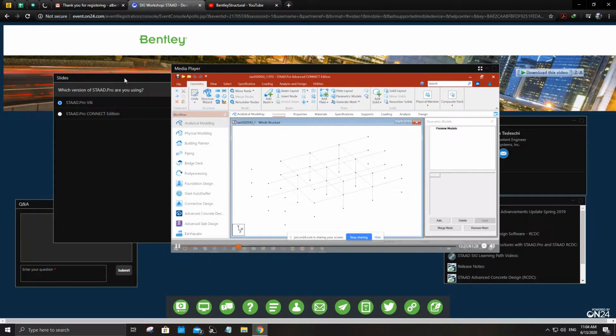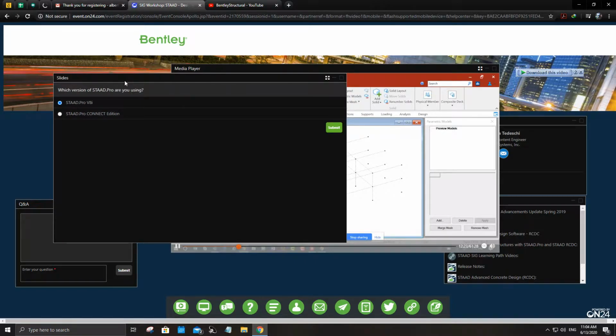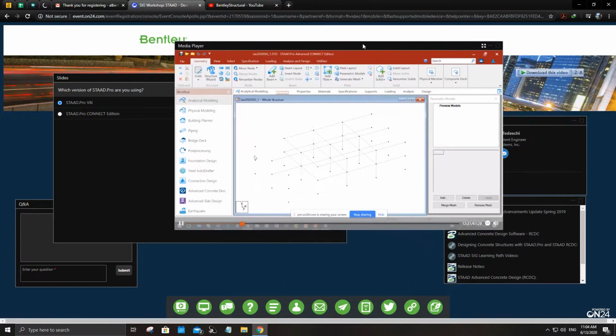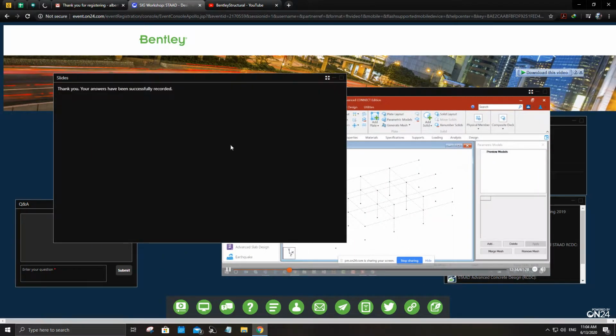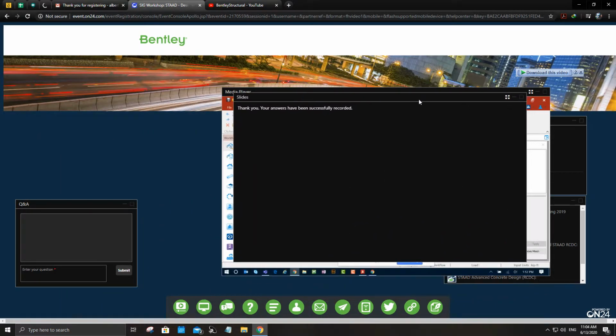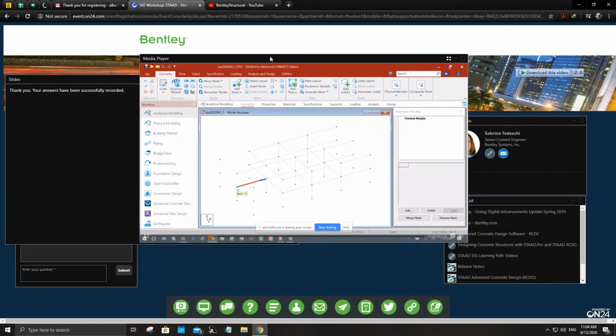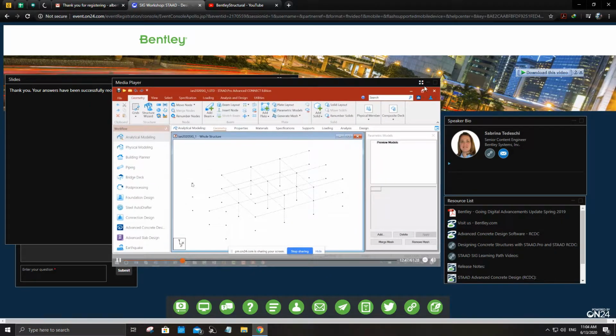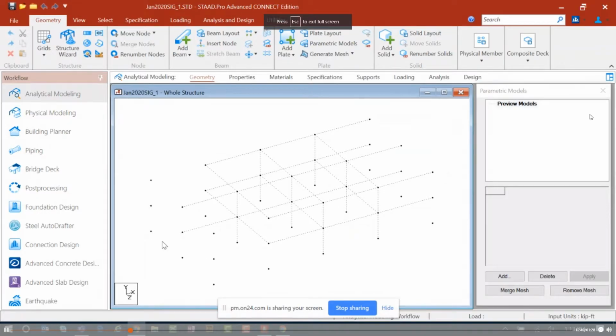So I'm going to create one wall for each level of the structure. What I did find by using this technique is that my mesh that is eventually generated becomes much more regular. Let's call this our west wall again. If we were to take a look at the west wall by ensuring that it's attached to all interior nodes, it gave me a very random mesh because I was trying to attach to this center node. If I have just one level at a time, that becomes just a very straight rectangle. There's actually no nodes in the plane of that. So my mesh actually became much more regular.